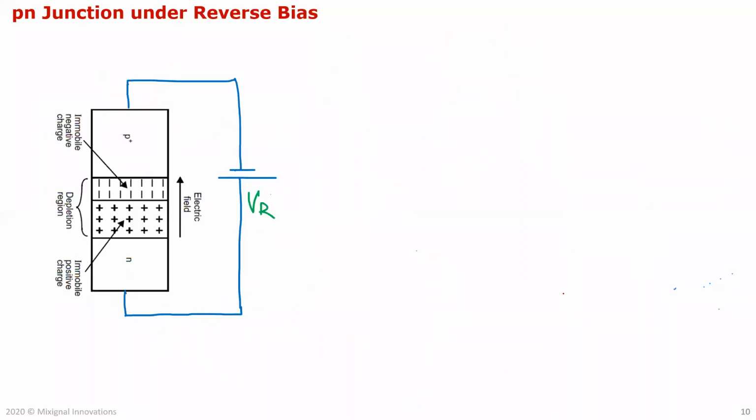We took the same PN junction, but instead of applying positive voltage here, we applied a negative voltage with respect to the N-type. What it does is it just enforces this electric field. As you keep increasing this VR, more electrons flow from the N-type to here because of the potential difference we are creating now. So essentially no current is flowing, charge is just building up.